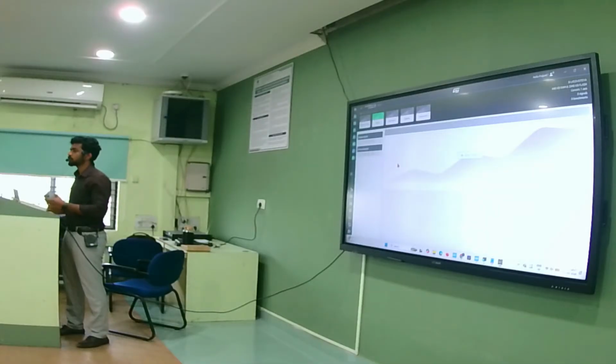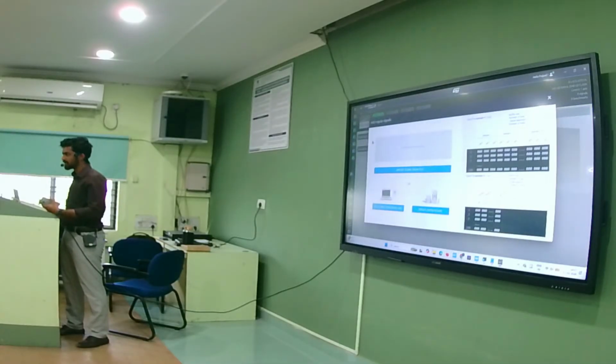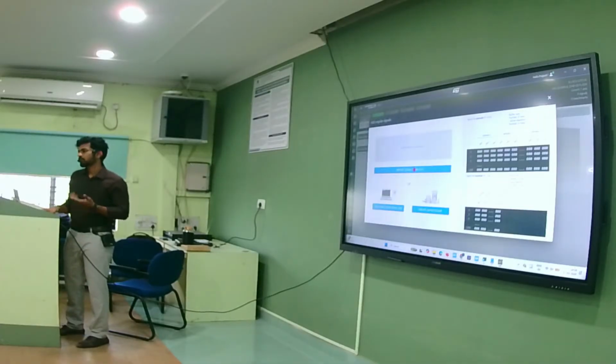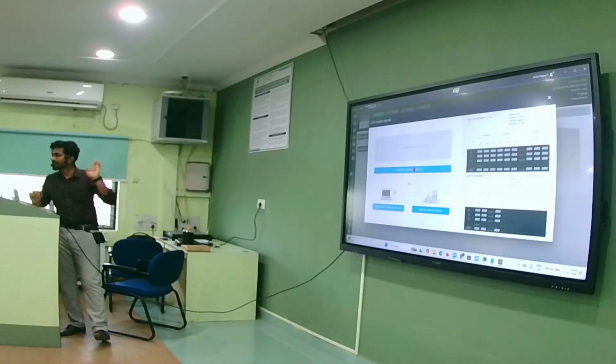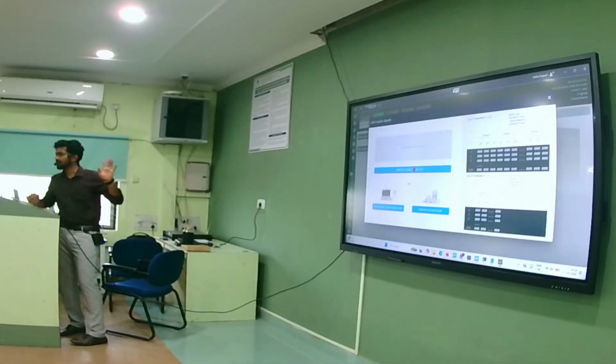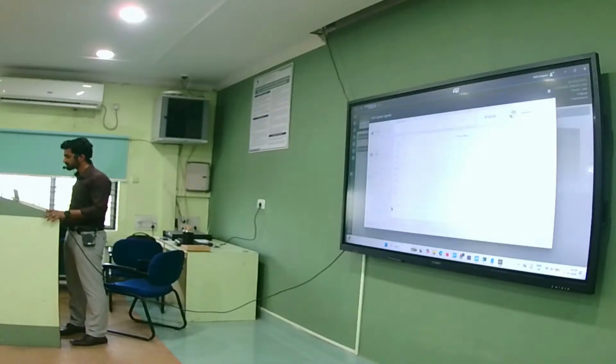Here, click on regular signal. Then which option will we select? If you want to add an already customized data set from a cable or some other site, then use import signal from file. Now there are no signals in our file, so we have to use log signal from serial USB. So click on log signal from serial USB.